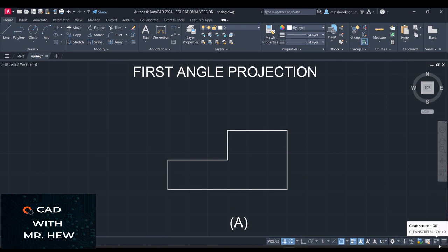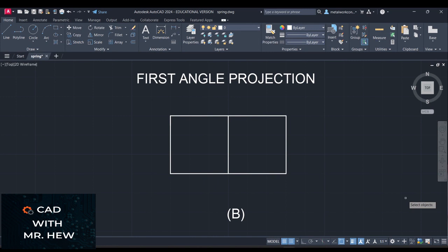So looking in the direction of A, as shown in the previous picture of the three-dimensional view drawn in isometric projection, when we look in the direction of the arrow A, this is the view that we would see of the object, okay? If you got it right, good job. Now the next thing we will move into is the view that we see looking from the direction B as indicated by the arrow, okay? The next step is to draw the view that we would see looking from above in the direction of the arrow labeled B. And this is the two-dimensional drawing that we would see looking from the direction of the arrow labeled B in the video that showed the three-dimensional object drawn in isometric projection.